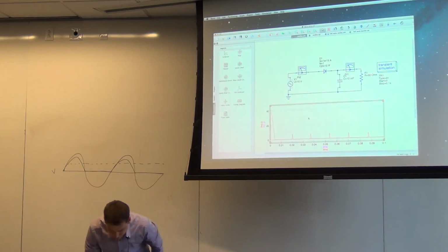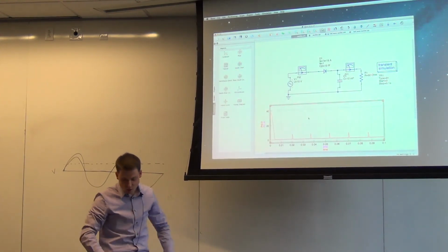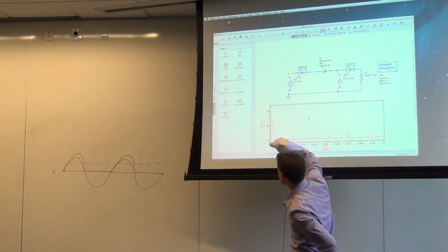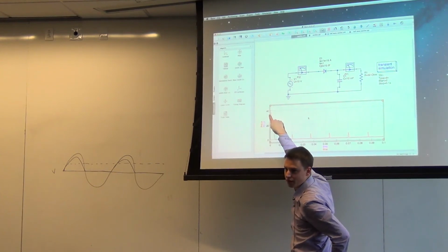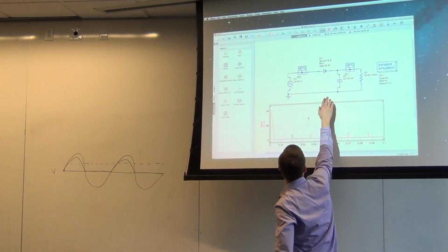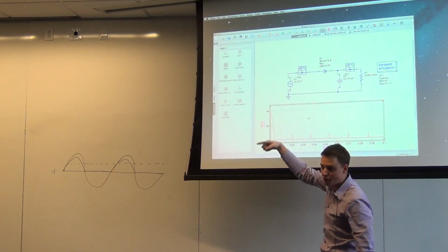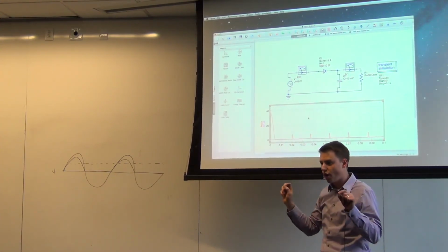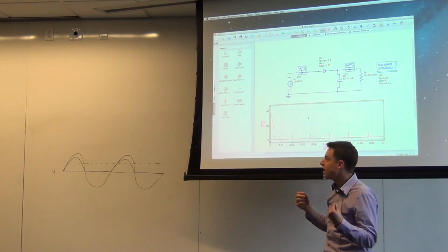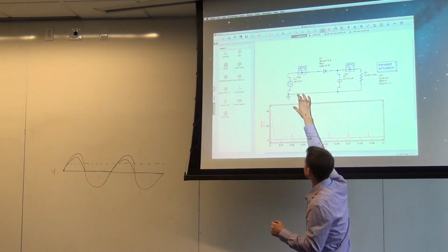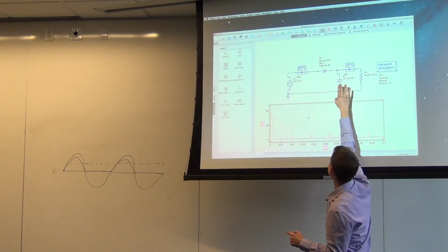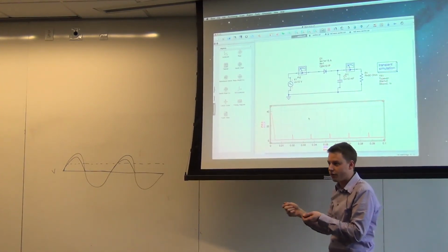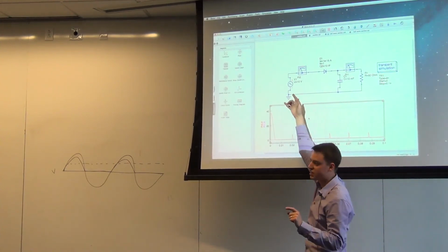Okay, so it's actually hard to see because they're on very different scales here. But essentially, what's happening is that at the time you're building up, first there's going to be a very high current through here because you're building up voltage. And essentially, you're both charging the capacitor and powering that thing. Then at subsequent times, you're only going to draw actual current when the voltage here is bigger than the voltage here. Otherwise, you just get the current from the capacitor, right? You won't be actually using this current at all.